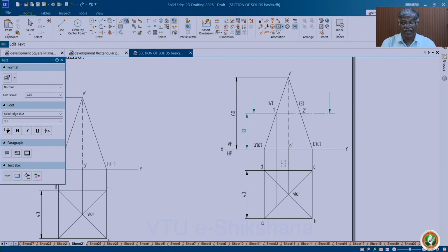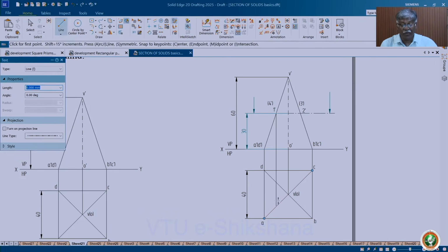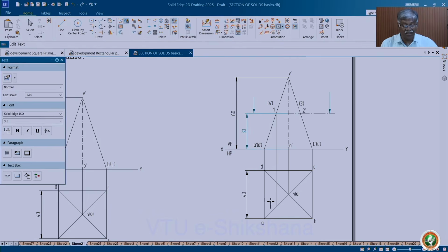Now, how to represent the same here? Yes, you just project onto the respective slant edges. See, I have projected 1 and 4 on VA and VD. So, what exactly is this point? Here is 1 that is intersecting at VA and this is 4. So, in the case of prisms, you know, it coincides with the same point because it is vertical. This is 1 and 4, because it is sloped, definitely you will get these points. Now, project 2 and 3.